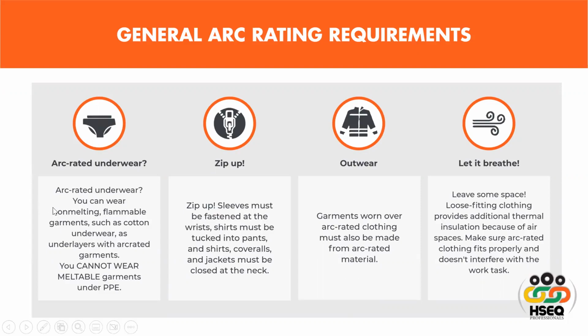But melting garments, which are made of silk or any other type of material, are not allowed to be used as underwear. So you cannot wear multiple garments under your PPE, because due to heat it will melt and then stick to the skin and body and continue to give you burns.